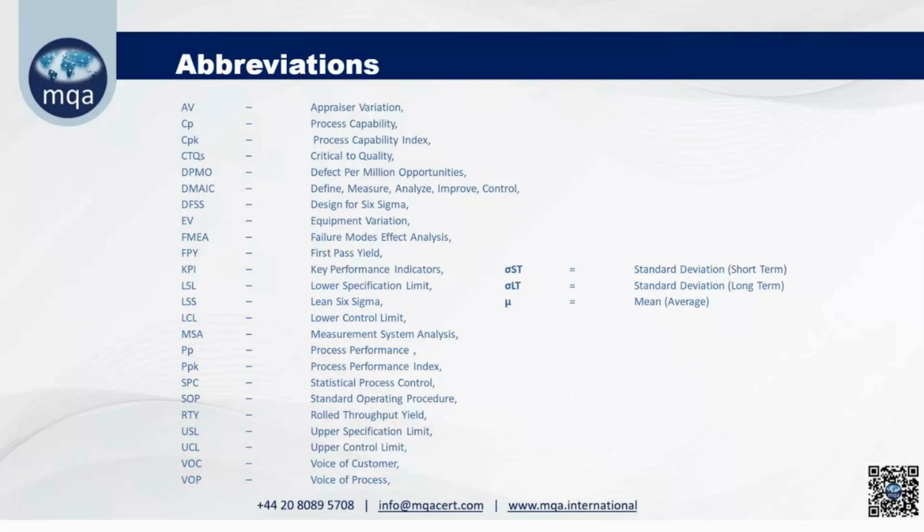Sorry, I'm lost. Yes? I got lost about what you mean by specification, trying to differentiate the lower specification. Specification is design specification. What is specification? Design, drawing. 10 plus minus 0.1 is the design specification, right? Which is specified by design. 10.1 is the upper specification, and 9.9 is the lower specification, right? Specification is defined by drawing, and control limits are defined by formula.